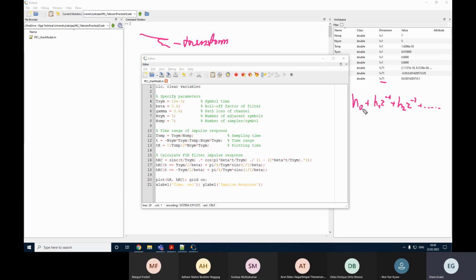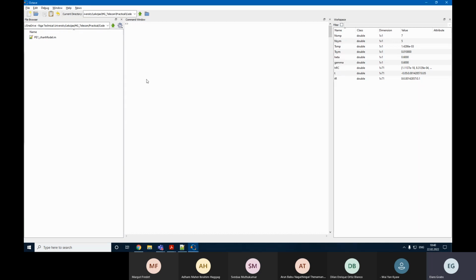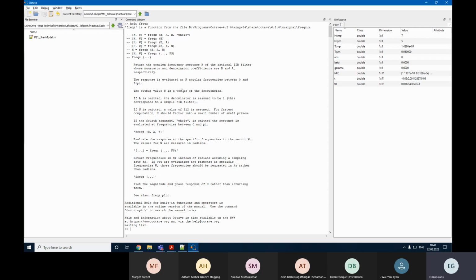And we need to actually replace this with a power of j omega t, where omega is from 0 to 1 or pi in MATLAB case, right? And accordingly show the plot for each of these points for complex number module and complex number argument. Yes. So basically we are going to do that now by using the so-called freqz function. So help freqz. This exactly does what we need by replacing each z with this range of frequencies.